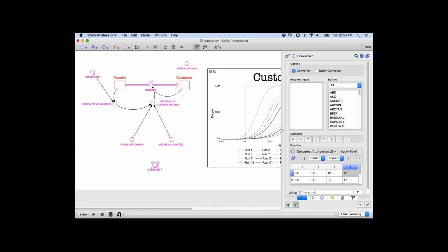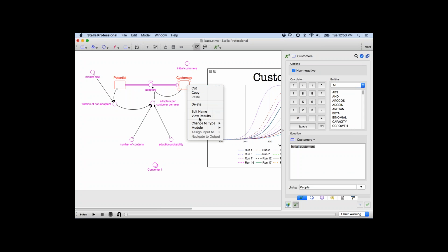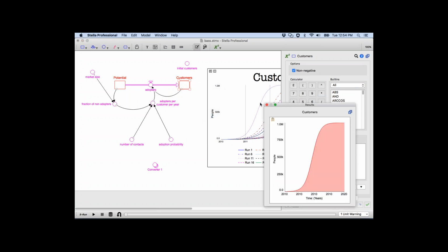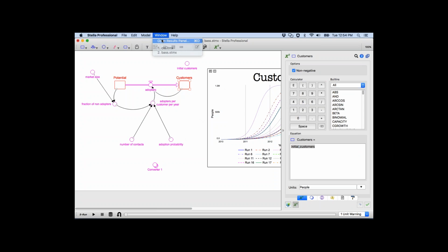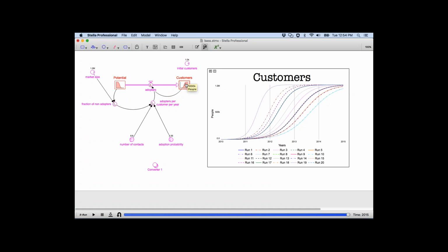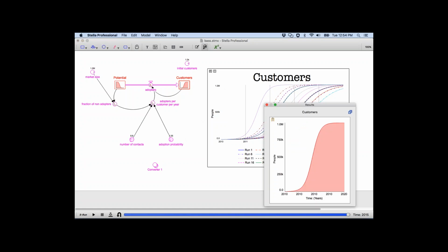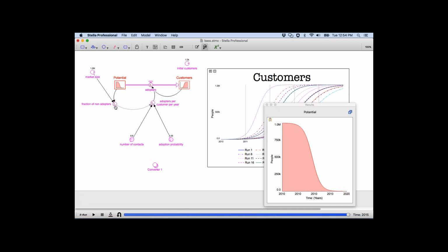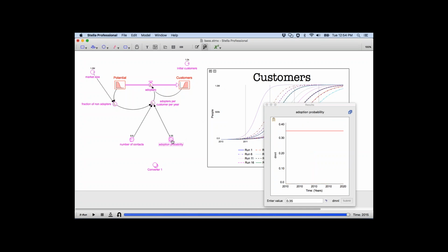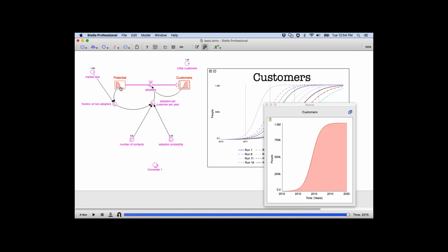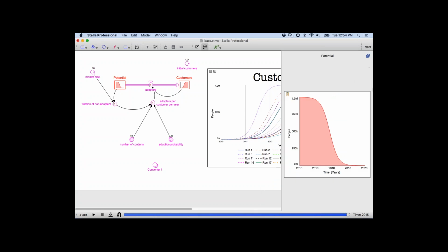Thank you, Billy. Simple question, how do you get the results panel to show again? The easiest way to do it for me, I like right-clicking. So I just right-click View Results. You can do it also by hitting Window, Open Results Panel. And I believe you can also do it when you're in Explore mode by hitting Alt-Click. So I can Alt-click on any variable, and it will change what's right there in the panel. But now, of course, that I've got the panel up, I don't need to hit Alt. I can just click along, and what's in that results panel will maintain. It will be based on what's selected.